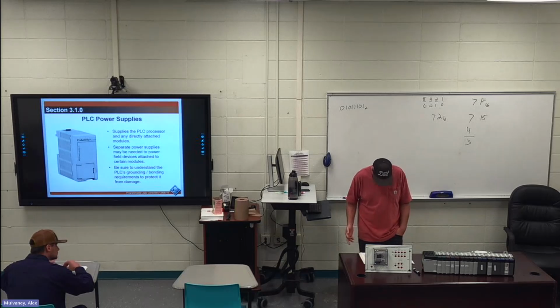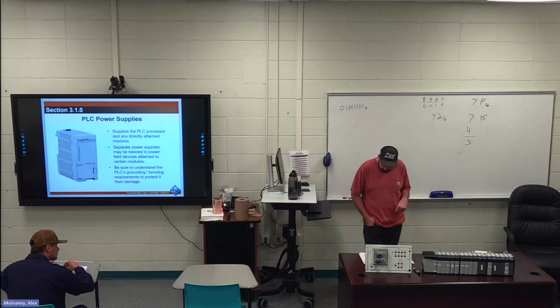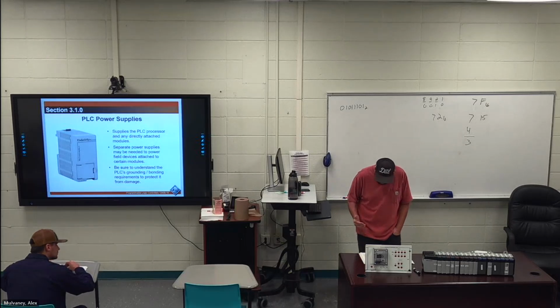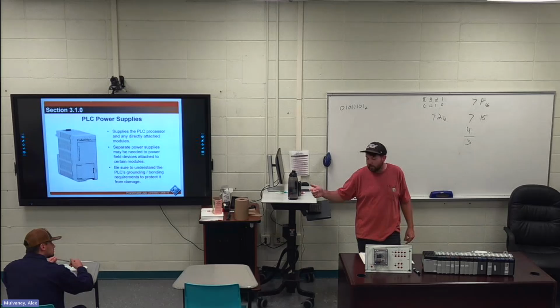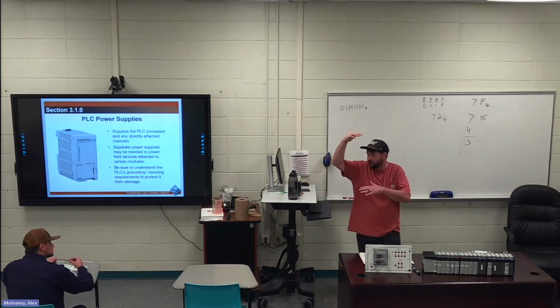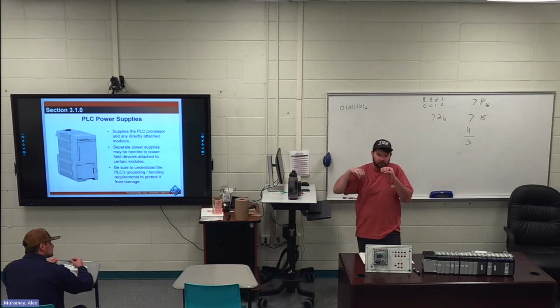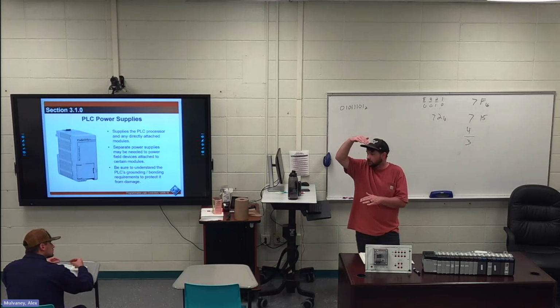Analog digital converter. We're going to talk about non-volatile memory versus volatile memory. A scan is important for a PLC. I don't remember the highlights of this one, but a scan, like where you asked that question. I said if something happens first before something else, it's going to override it. Your alarms and permissives are always written above other stuff so that they override them because they're more important.